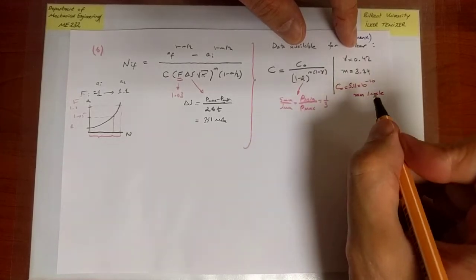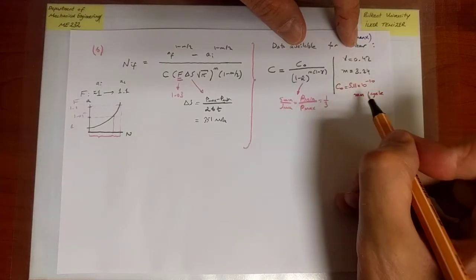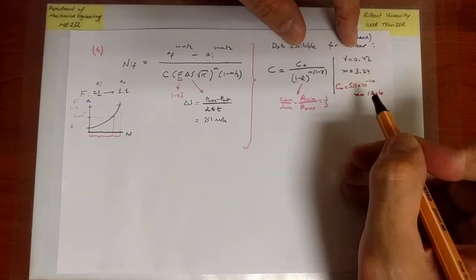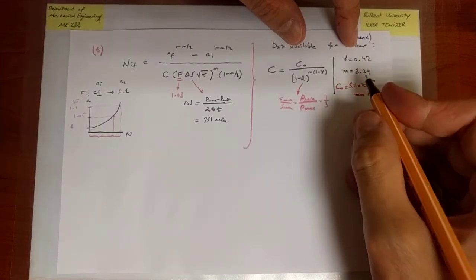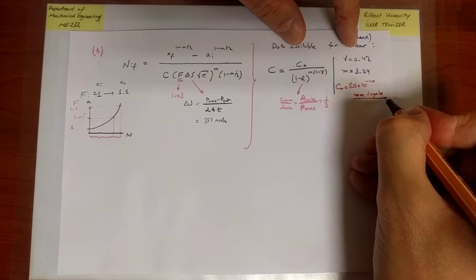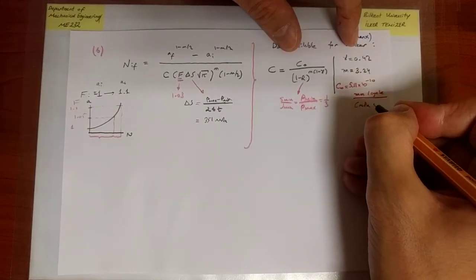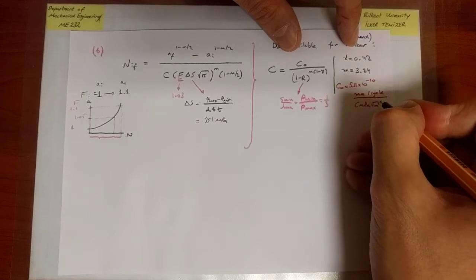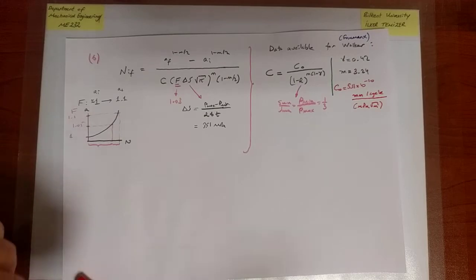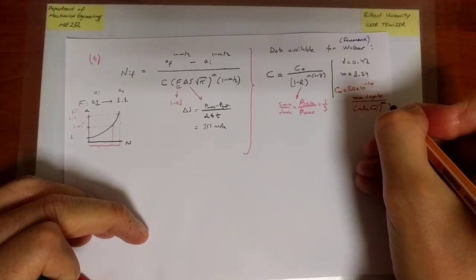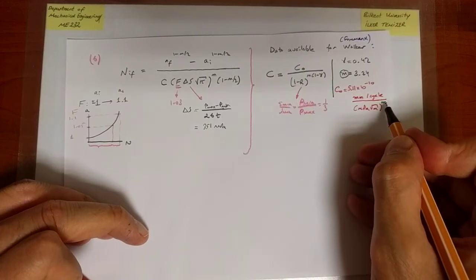Okay, remember, crack growth rate is usually given in terms of millimeters per cycle. So C naught is a parameter that goes into the crack growth rate, but it's not crack growth rate units by itself for C naught. To be consistent with the equation, the units it has is MPa square root meters to the power M, let me write this explicitly. This M is this M. Okay, it's not meters.